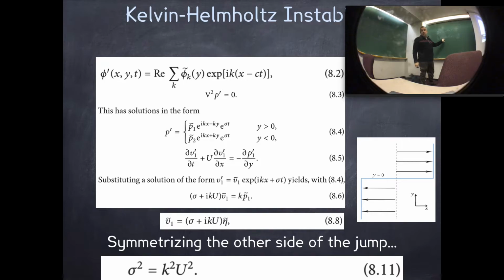The other important equation is the vorticity equation, which we would get by taking the curl of this equation. So let's see how that goes. We get the vorticity, we get the curl here. What happens to this term if I take the curl? 0. And then this one gives us that complicated thing where there's vorticity dotted into the gradient of u plus u dot gradient of vorticity, right? This is the tilting and stretching terms. Let's hold on to this for a moment and see what happens to it. Okay.